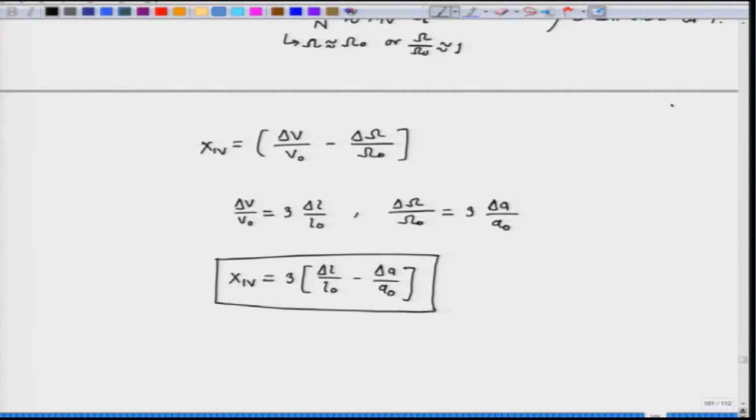So, we need to use X-ray diffractometer, and typically there are dedicated X-ray diffractometers which are equipped with measurement of small changes in linear dimensions of the metal piece. At the same time, the change in lattice parameter is tracked and they are related to the vacancy concentration. Of course, we also need the XRD to be equipped with high temperature measurements, so that we can do the measurements at different temperatures.